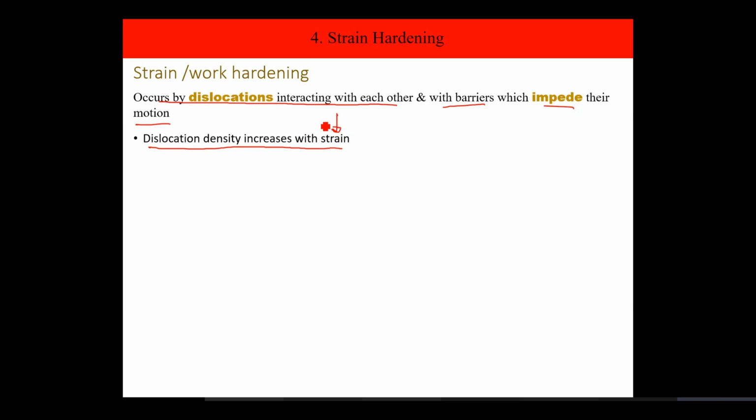If we look at the dislocation density formula, it is basically the total length of dislocation divided by the unit volume in which that dislocation length exists. For an annealed sample, which is a stress-free, soft, ductile sample, the dislocation density is about 10^5 or 10^6 centimeter per centimeter cube of the material.